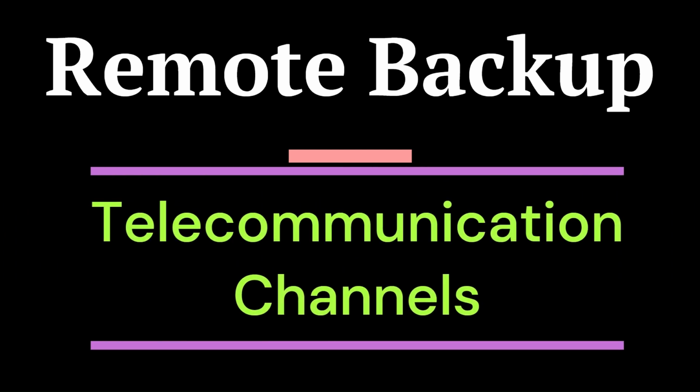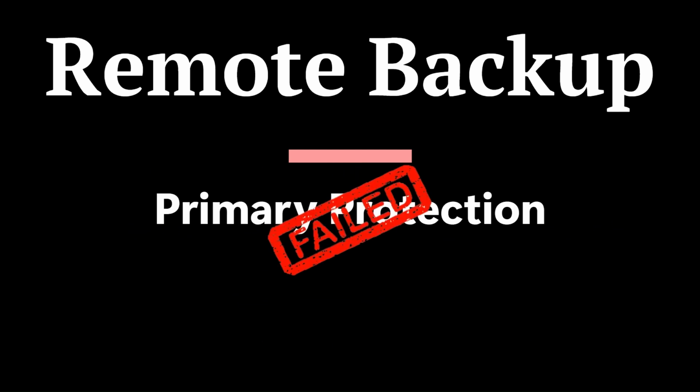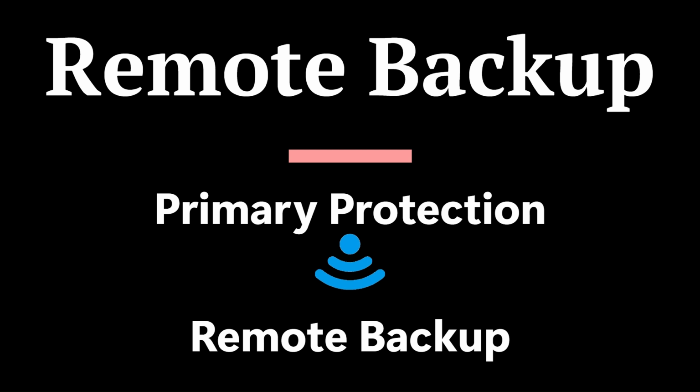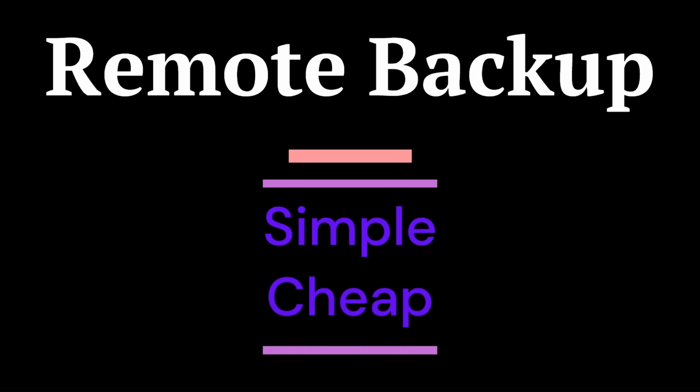Remote backup systems often use telecommunication channels to communicate with the primary protection devices and respond to fault signals. If the primary protection fails to clear a fault, the remote backup will receive the signal and initiate a trip to clear the faulty section. This is the simplest and cheapest form of backup protection and widely used for transmission lines.